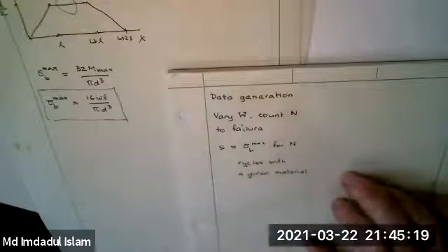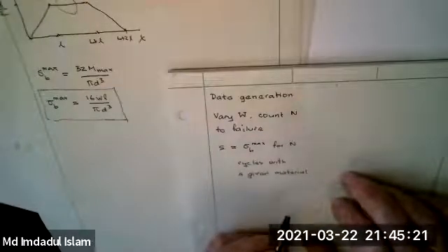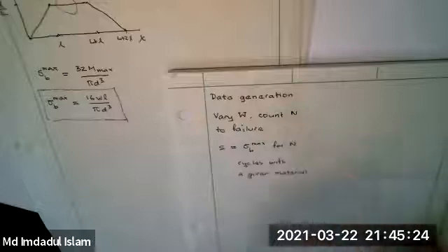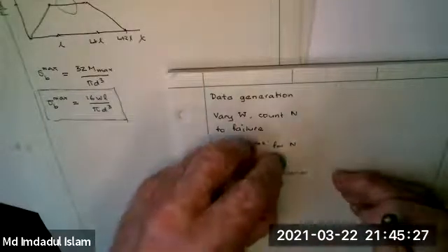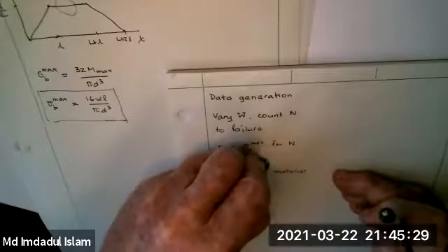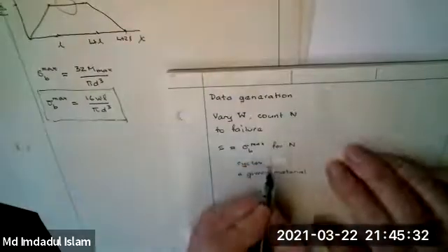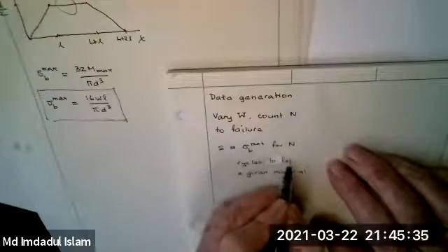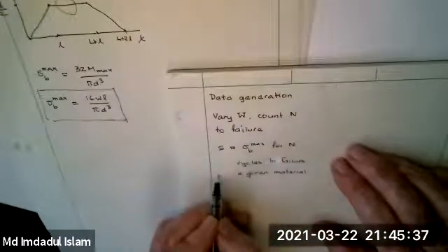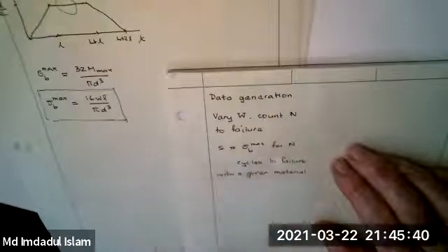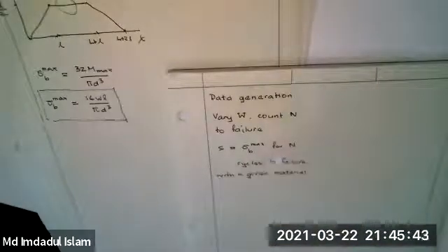N cycles to failure. Perhaps I should have put that. Let me fix that. Let me reiterate. And this is what the data looks like for steels. Most of the testing that's been done, fatigue testing over the years, is for steels. There's quite a lot of testing for aluminum. There's also testing for basically every other metal that's used. But we'll deal with steels to start with.